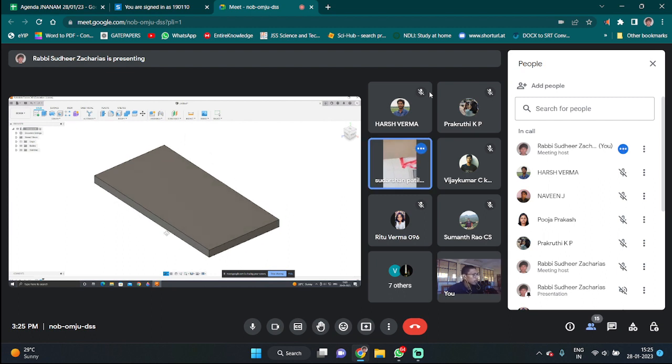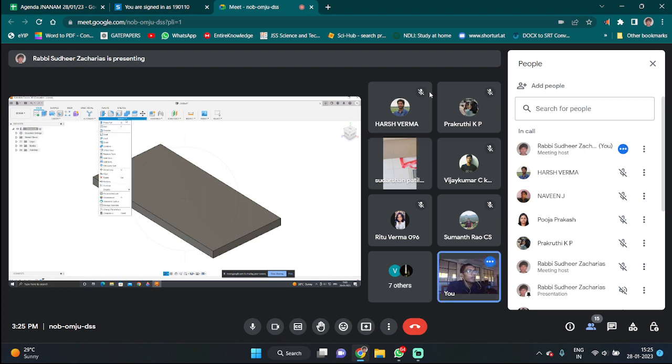So many of our phones, the latest phones, have these curved boundaries at the edges, right? We don't have a sharp cut. We usually have curved boundaries, the smooth finish, right? So for that, over here, there is an option called modify. If you just click on it, there is something called fillet. Fillet is basically like the sandpaper we use in real life. For example, if you have done projects with some thermocol or something, you use sandpaper to polish it. So it smoothens the boundaries.